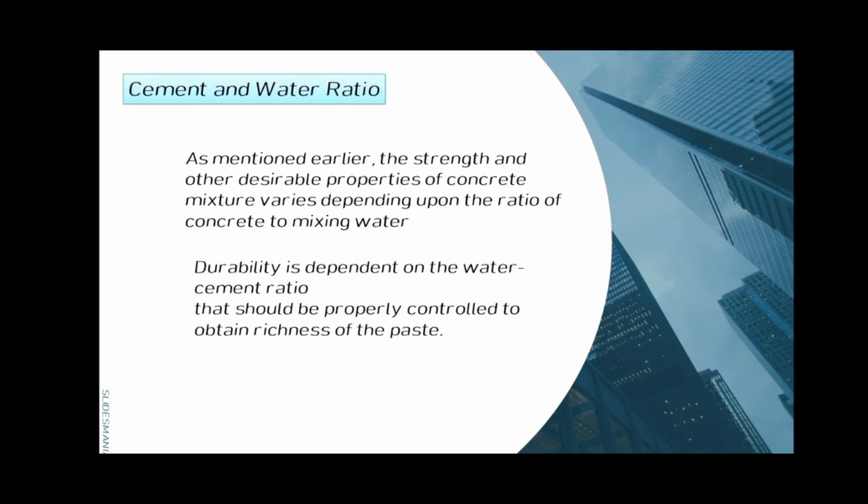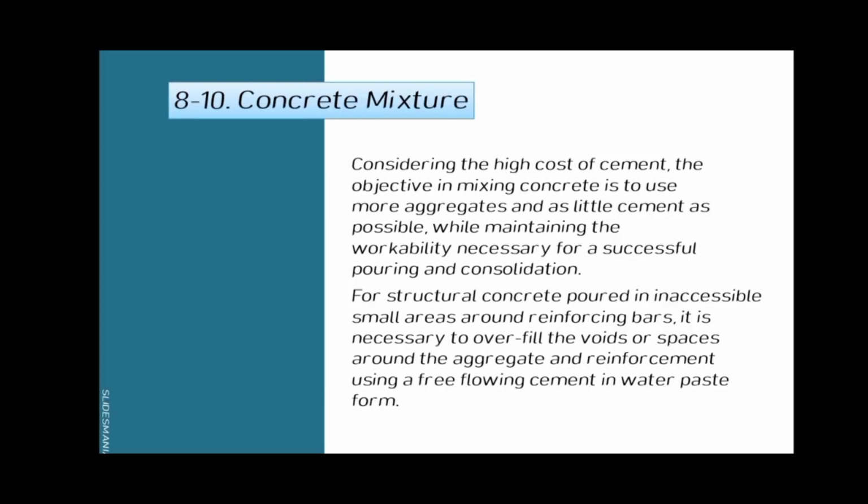As mentioned earlier, the strength and the other desirable properties of the concrete mixture vary depending upon the ratio of the cement to mixing water. So durability is dependent on the water-cement ratio, which should be properly controlled to obtain richness of the paste in the concrete mixture.